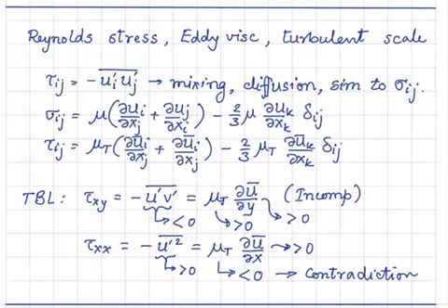So we have to keep in mind that this formula is not always valid. It works well for turbulent boundary layers, canonical flows, simple, well-studied flows like boundary layers, free shear layers, wakes, and so on and so forth. It does not work in many other situations, and one particular case is shock waves. So we will see how that comes up at a later stage. Okay, knowing that, let's move on to see how to compute eddy viscosity.